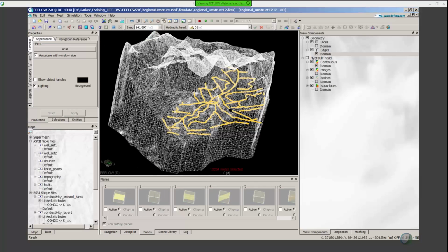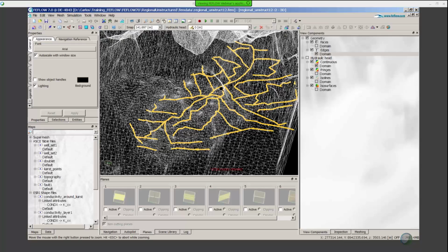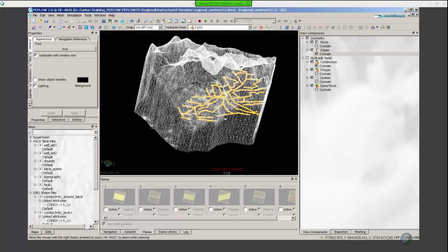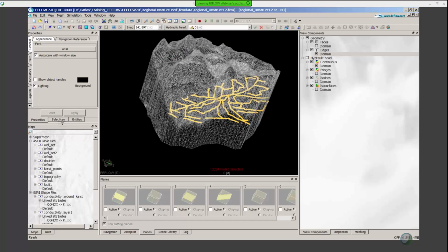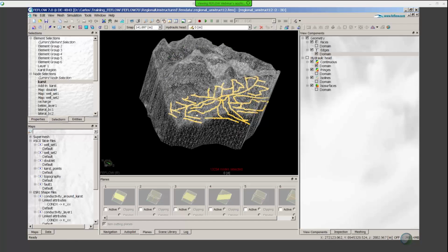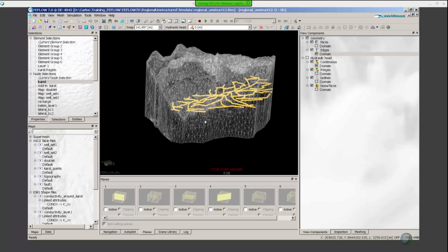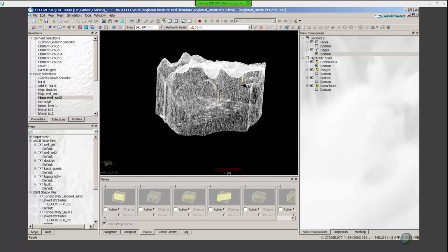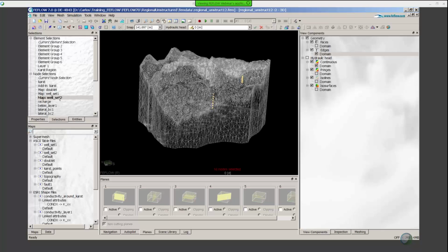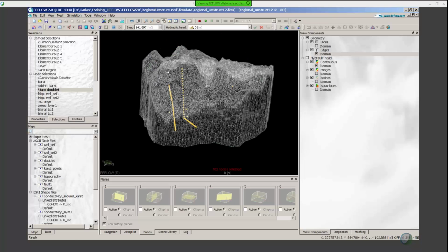You can now have your karst system inside the model domain, and we simply remeshed one section of the model domain. If you want to include inclined wells, the same principle applies: you need to remesh the location where you have your wells. This is also an example that we are doing in our training course.